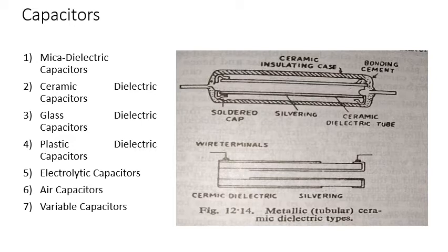The main characteristics of this capacitor are low power factor, high voltage operation, and long-term stability at room temperature. Precision mica capacitors are used as substandards and can be adjusted to better than 0.01% stability for values over 1 microfarad. They are sealed in cases to protect against moisture.